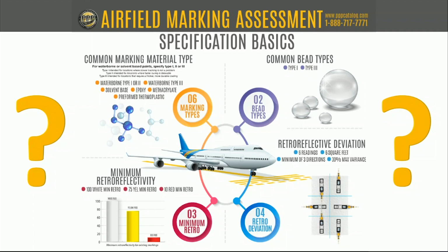But specific to your new construction projects where you have a contractor, you might have a consultant engineer that is the project manager, and your RPR or resident project representative. That is something that really falls under the consultant engineer's purview. Frankly, you do not want a contractor measuring their own work and saying, hey, everything's good, don't worry. You need somebody independent. That is something that should fall in that quality assurance category, and it should be done independently. The RPR can do it.